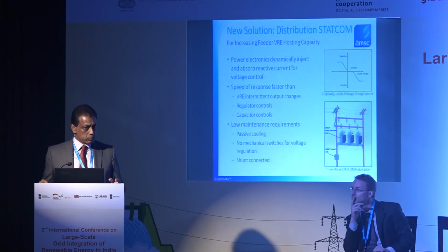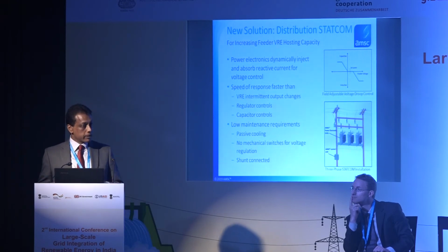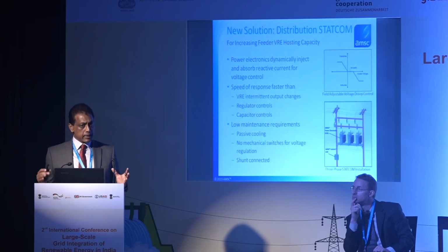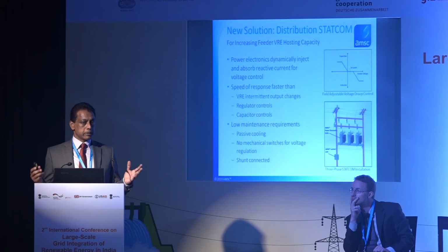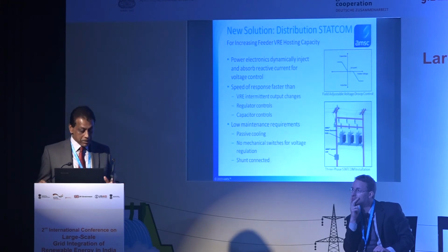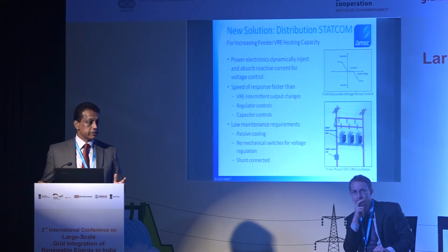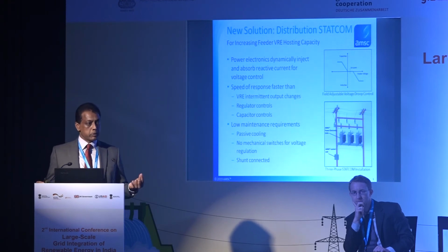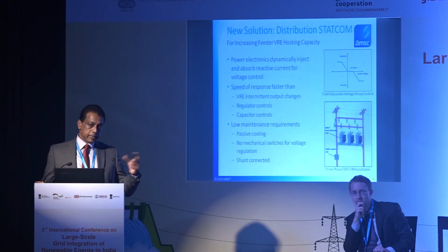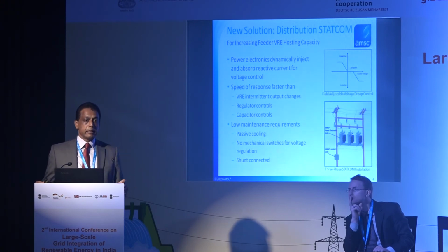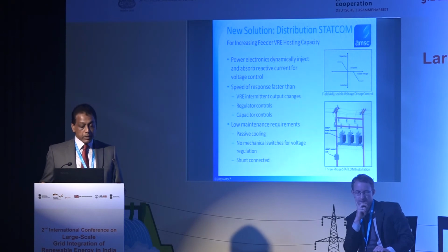looking at how we can take that technology to the distribution system with the advent of a lot of DER coming in. So it's really taking that large traditional STATCOM. If you are not sure what a STATCOM is, I'm sure most of you know, but a STATCOM is essentially a power electronic device that's able to provide reactive current in capacitive mode or inductive mode, and the output of that device can be controlled infinitely between the rating of what it is.